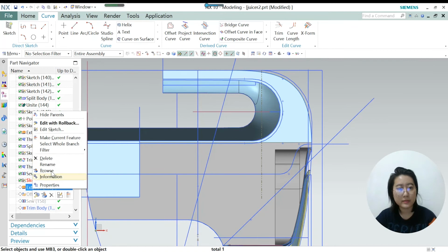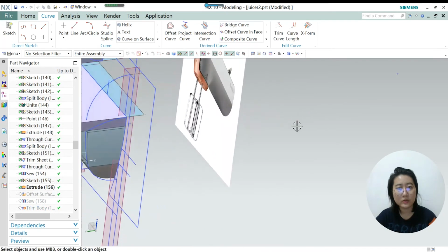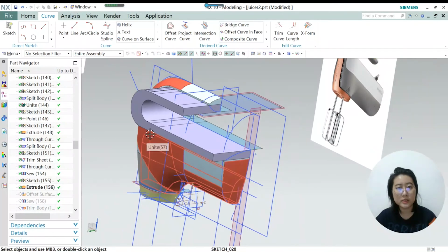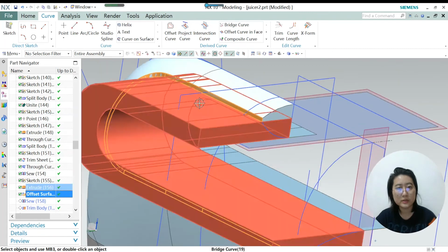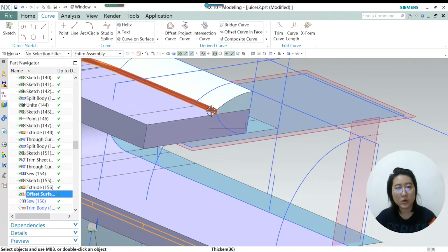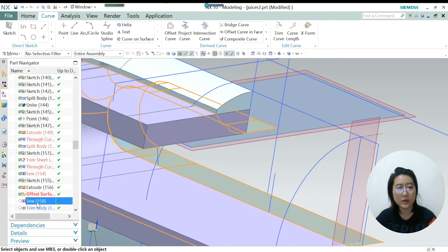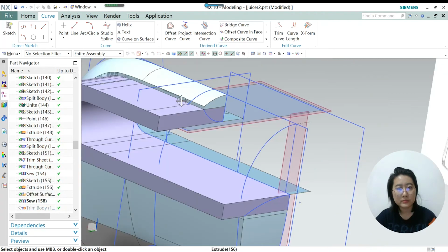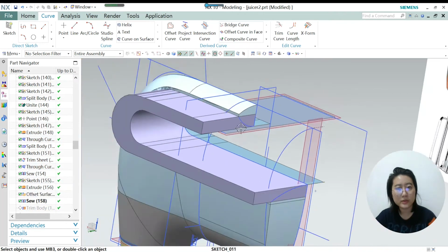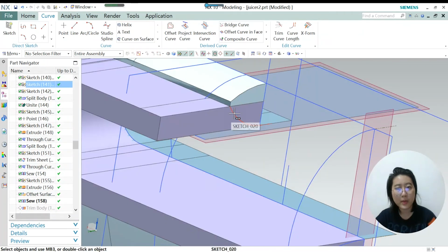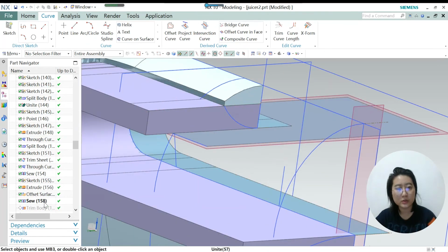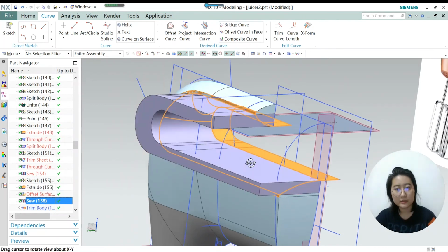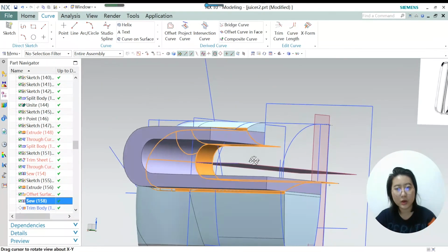In the next step, I'm trying to extrude this sketch, and in offset surface, I copy one surface. By using offset surface, you need to set the distance to 0. So next step, I'm sewing this surface with this through curve mesh surface and this surface together. So if I click the sew order, you could see the whole surface here.